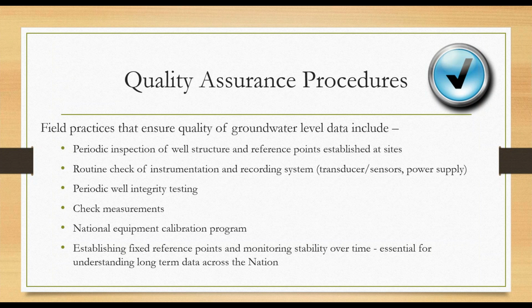If your site is involved in routine data collection, you have to do well integrity testing to make sure that well is still in connection with the aquifer. Also, establishing fixed reference points and monitoring the stability of those reference points over time is essential for understanding the long-term data across the nation.